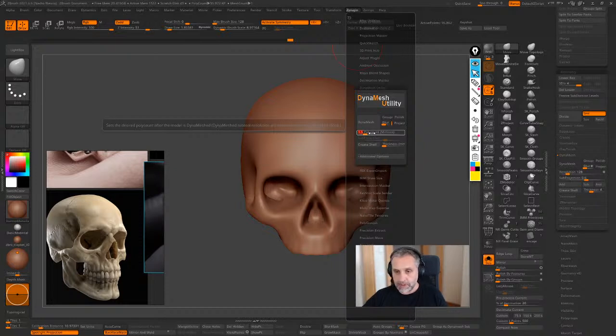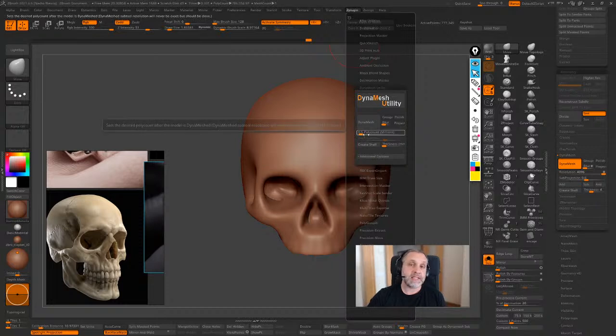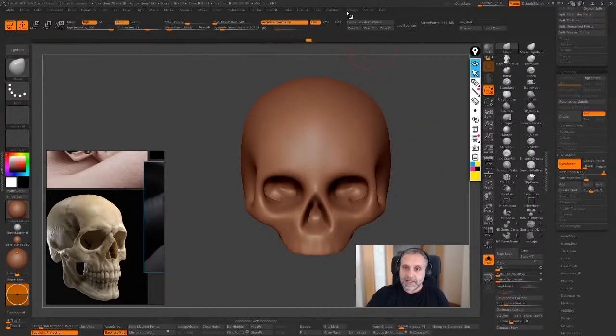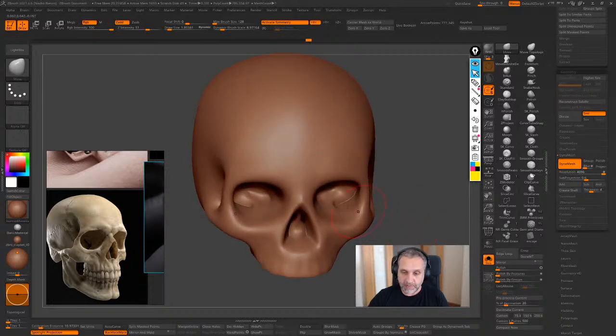So let's say 500,000, 0.5 is a good starting point. I don't want any blurring, so I'm gonna turn this off. I'm gonna set the blur to 0. Let's create Dynamesh. The good thing about this plugin is where I decide the quantity of points that I'm looking for, I decide to start from a mesh of 500,000 points. So when I click here instead of here, the plugin is giving to me the exact resolution for the amount of polygons which I am looking for.